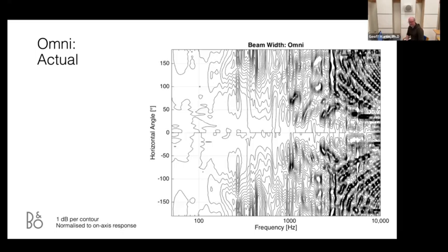That's because those tweeters are just so far apart from each other that if you do use them to send energy in all directions, there's no avoiding the lobing. Of course, if we wanted to make an omnidirectional speaker, it would have been a very different hardware configuration. So like I said, there was no real intention to make an omni speaker. This is just a party mode for what is effectively a narrow and wide speaker.